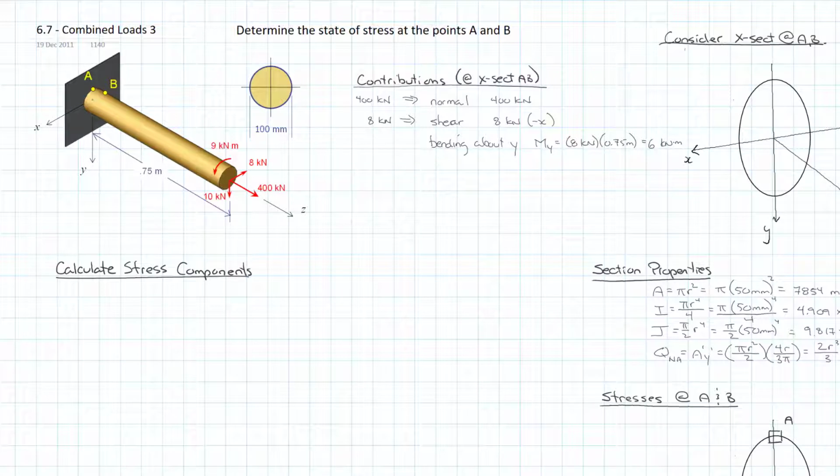So let's look at the 10 kilonewton force. Of course, it's going to provide a shear contribution of 10 kilonewtons, going in the positive y direction. Then it also provides bending, right?